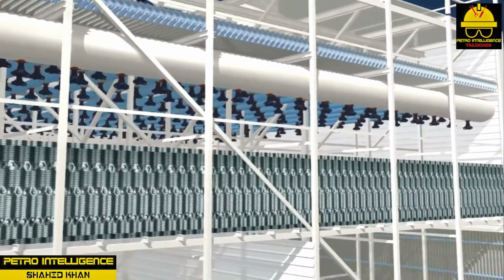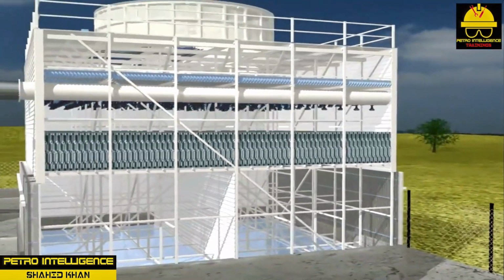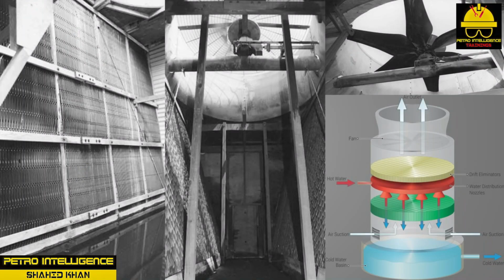Induced draft towers can circulate airflow horizontally, crossflow, or vertically, counterflow. During crossflow operation, drift eliminators are located in the center of the tower to reduce water loss. Counterflow operations force air vertically across a solid area of fill, and drift eliminators are located above the fill and water distribution headers.